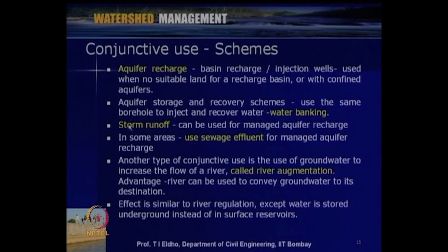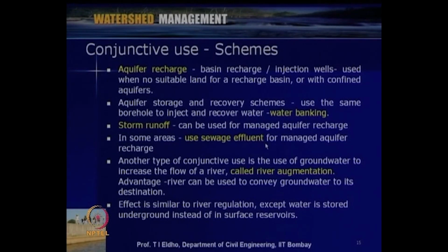Then especially in most watersheds, can we effectively utilize the storm runoff for recharging the aquifer systems? Through natural recharge, by improving the natural recharge, or we can go for artificial recharge structures. Then, depending upon the area, we can use sewage effluent, especially when the effluent is of good quality after the various treatment processes.